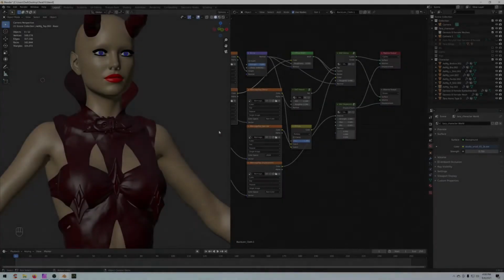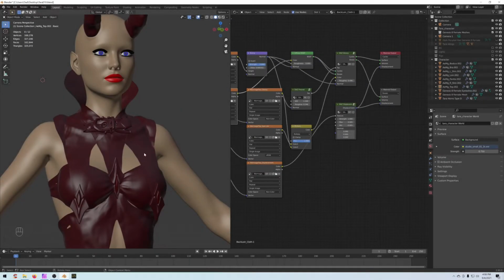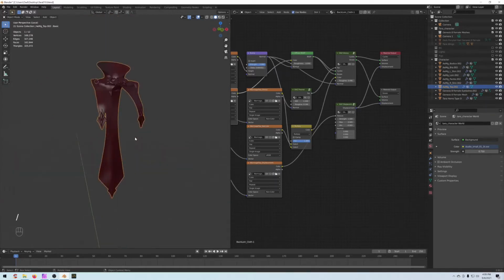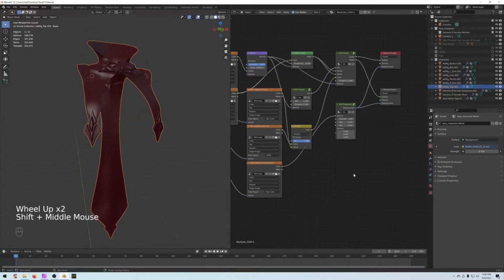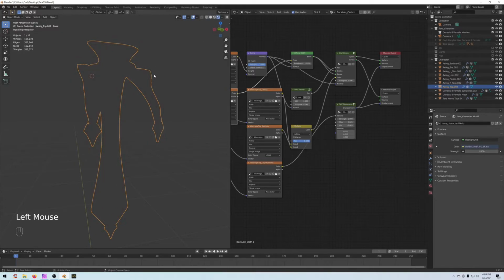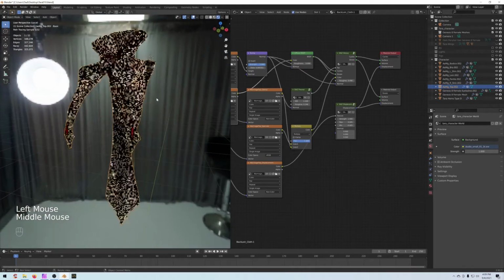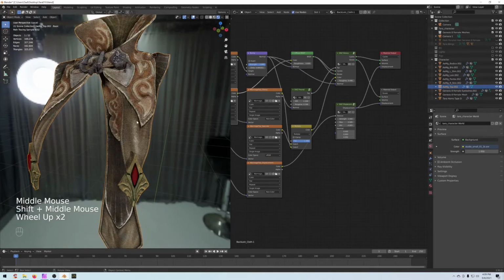Next we'll work on the character clothing materials. So we'll just select one here, and we'll hit the / to isolate it. And that's why I like using HDRIs as our light source. Bump that up to 1, because you can isolate each individual piece pretty easily and adjust the materials.